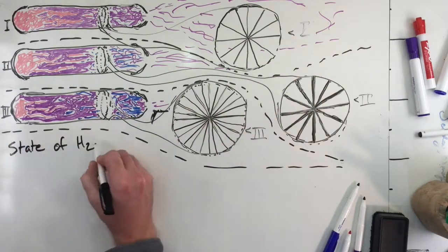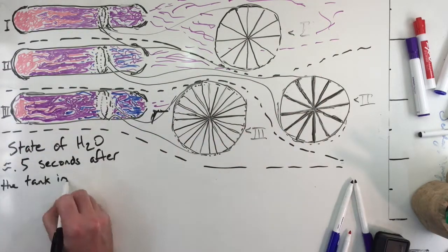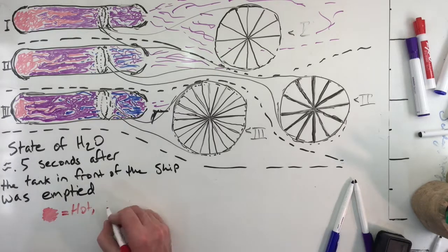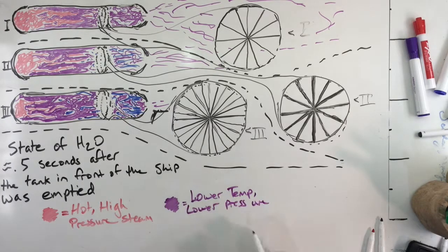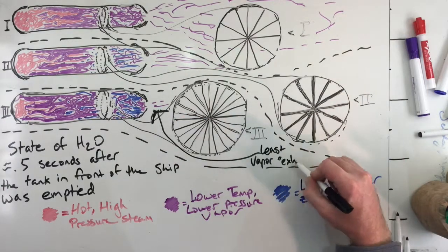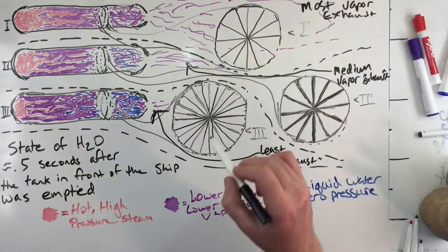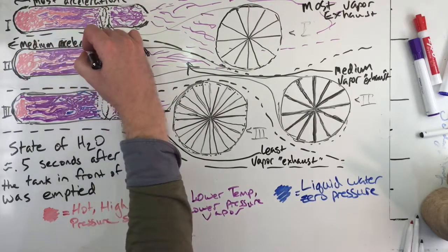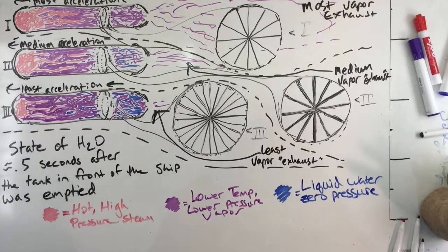But it also has more surface area for the steam to hit on its way down the channels between the baffles, so it can condense the most of the three. It also has a design that's going to create more turbulence, which I'll get into later. Of the three designs, I think that the top one will get the most acceleration out of the steam generated